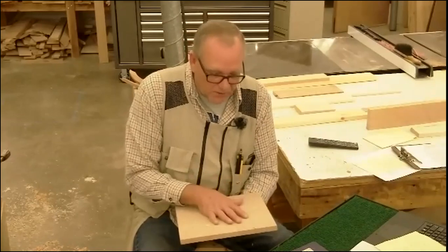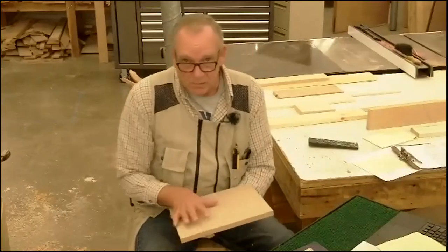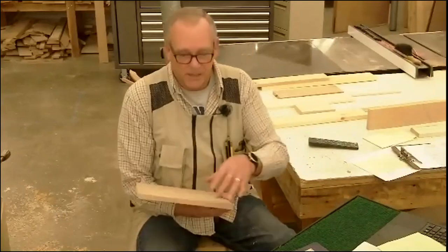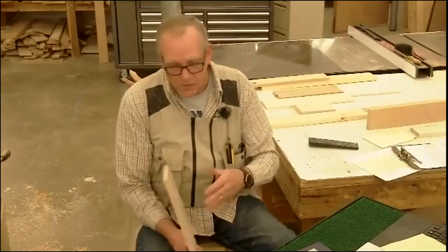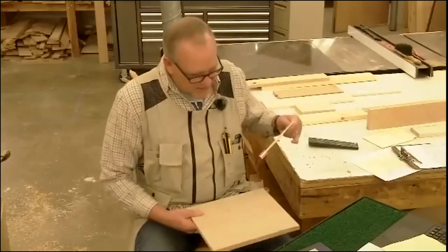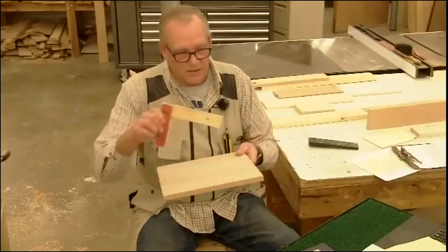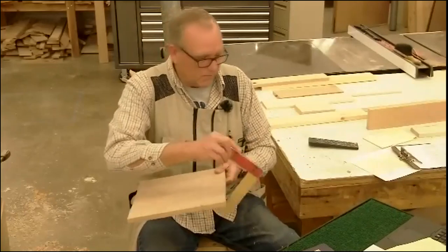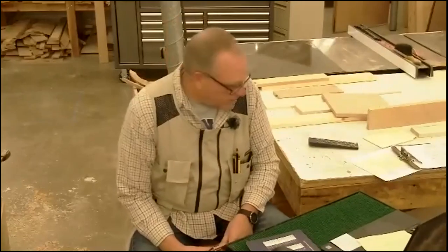You can also safely assume that the faces of these boards are going to be flat. They're also parallel to each other. So we don't need to joint a face. It's already flat. We don't need to plane the opposite face. It's already a consistent thickness no matter where you measure it, and that means that the two faces are parallel to each other. We do not need to joint an edge because it's already safely 90 degrees to that face, 90 degrees to that face, 90 degrees to that face, 90 degrees to that face. So you don't need to worry about jointing sheet goods. We do not joint sheet goods, okay?